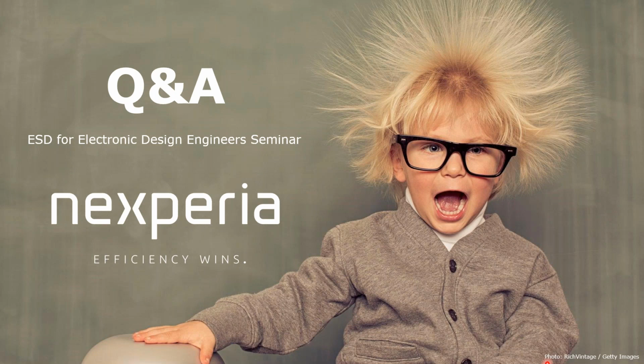Next question: based on your photos of failure models, an ESD failure is not only pinholes but also burnt polysilicon or metals. Yes, that's true. Basically anything can be destroyed. You even see melted bond wires, not directly from ordinary ESD events, but from surge events, for example. But afterwards, it's impossible to distinguish what actually happened when the IC was destroyed.